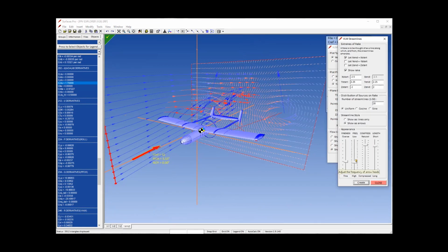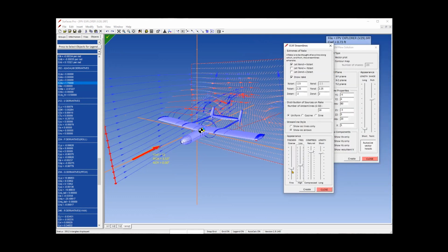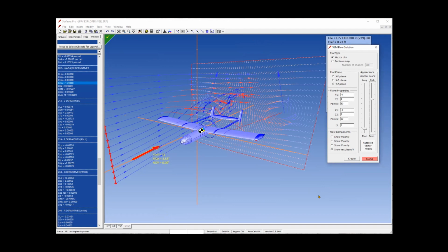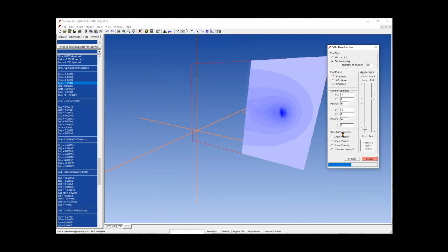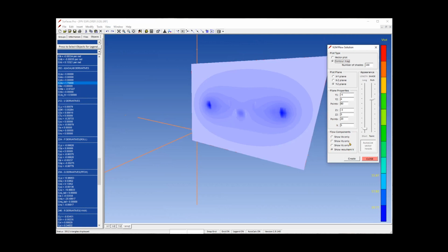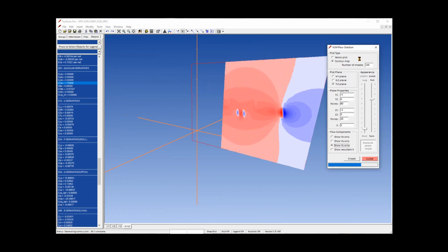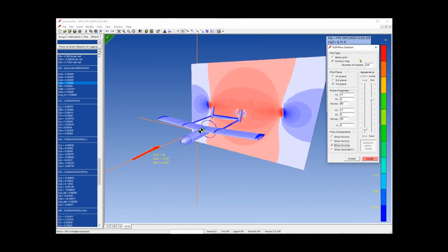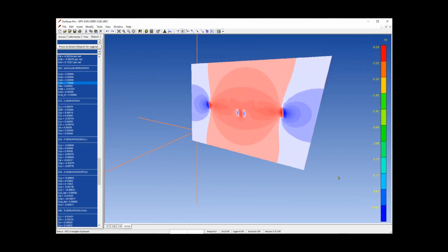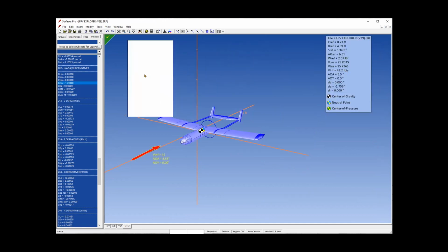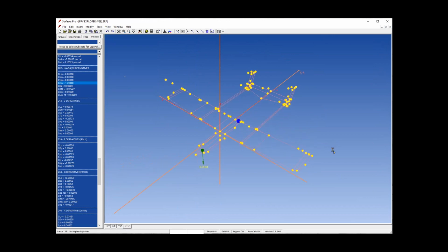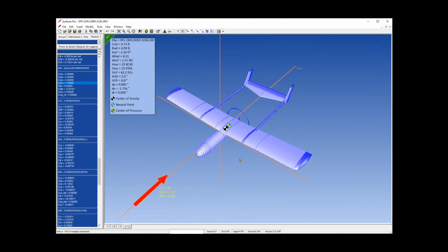Let's turn off the streamlines and plot the flow field as a contour map. This shows the total velocity. This only shows the vertical flow components. Red represents down moving airflow, the blue up moving airflow. The primary improvements in these two tools is that the flow arrows are persistent, allowing the user to reorient the viewpoint for best view. The flow field image remains until the user closes the form.